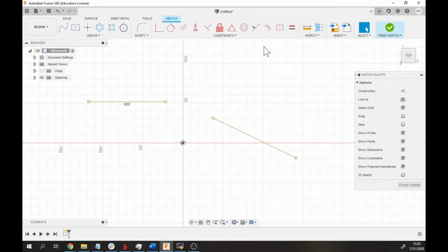So essentially what the Curvature Tool is for, you probably won't be using it too much if you're just getting into 3D modeling, and especially if you're using it for 3D printing. It's used largely when you're doing CNC machining and you need to have your curves line up with the commands that that machine uses. So what it's used for, it only applies to splines, is that you'll make a spline, say between these 2 points here.